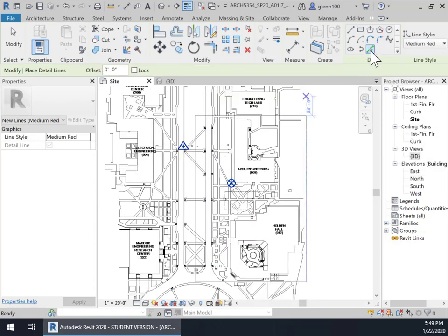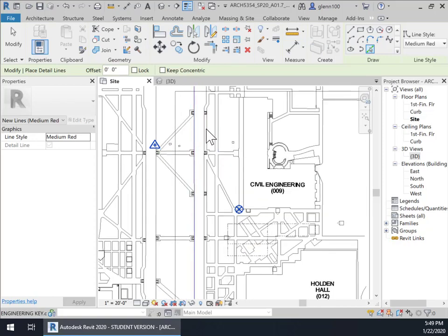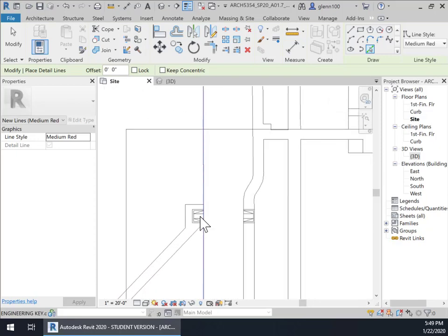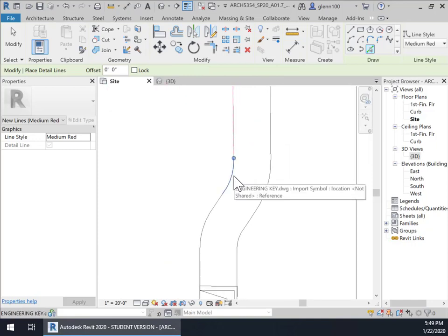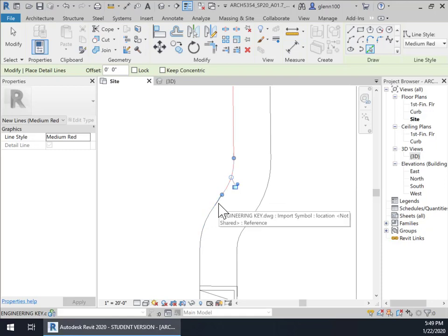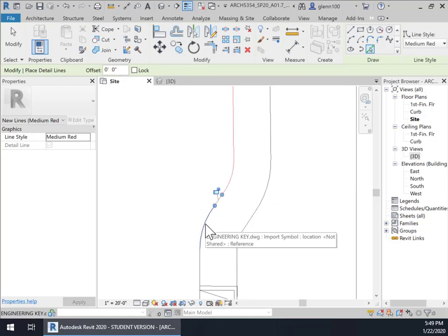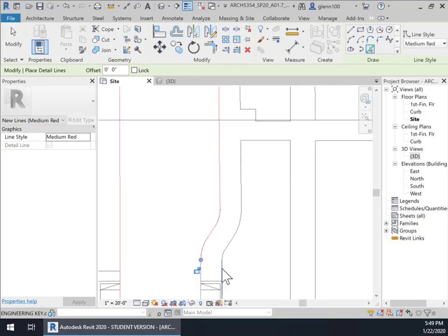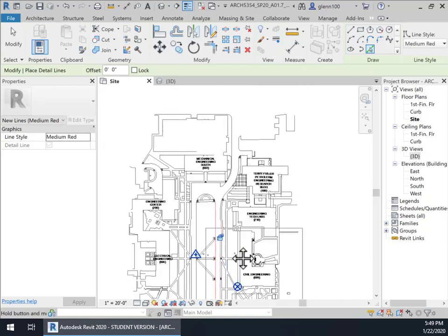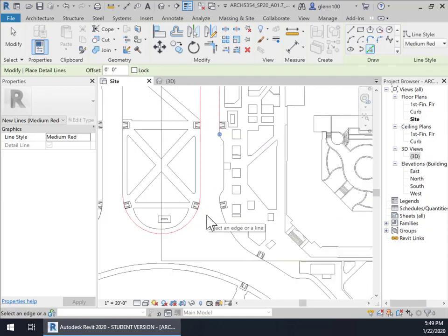And then I'm going to select pick, pick lines, and I'm going to pick this line right here and this arc right here to represent what I'm going to slice out of that side. And then I'm going to come down here and zoom in a little bit more because it's a little trickier now. I'm going to pick this and that little segment. See, if I'd stayed zoomed out, I might have missed that little segment, and that wouldn't have been good. And then I'm going to select this line right here, which should go all the way to the end down here. Okay.